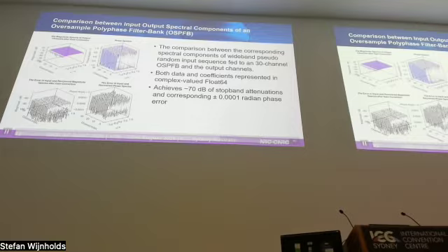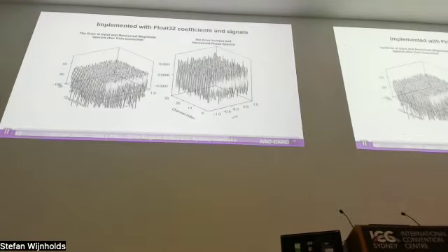Note that to align the input and output phase spectra, the output sample sequence must be shifted to account for the propagation delay through the polyphase filters. The 70 dB suppression of aliasing signal and approximately 0.0001 radian phase error indicate that the OSPFB had been implemented correctly.